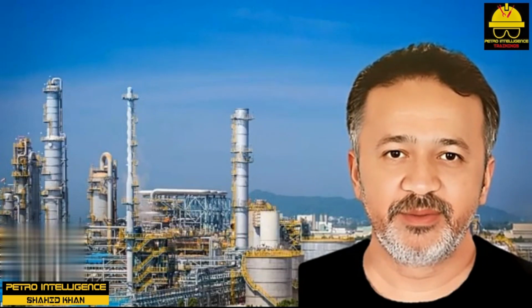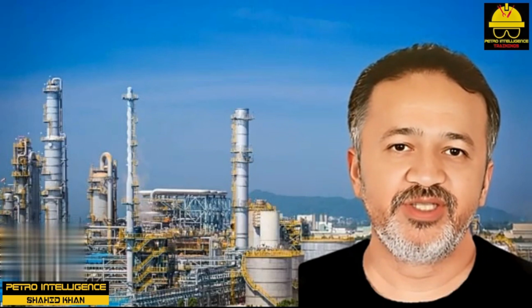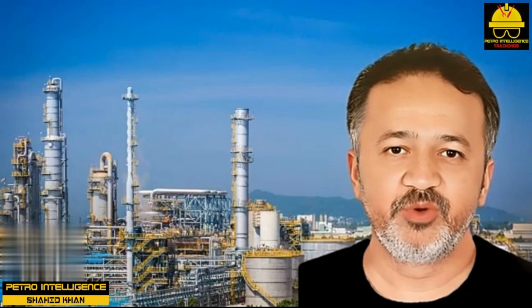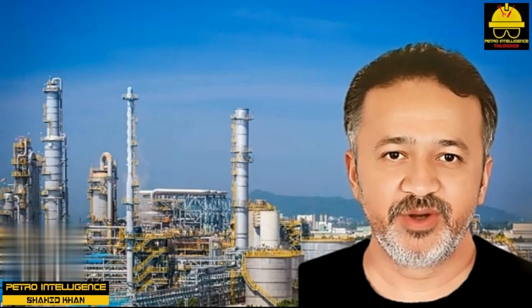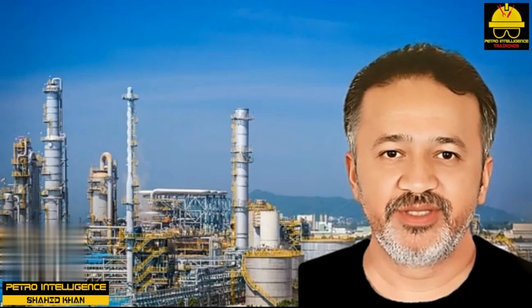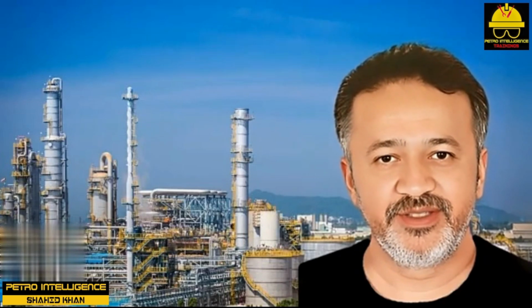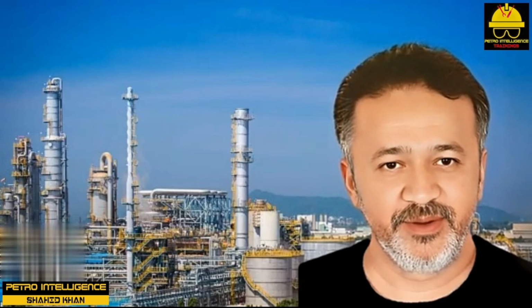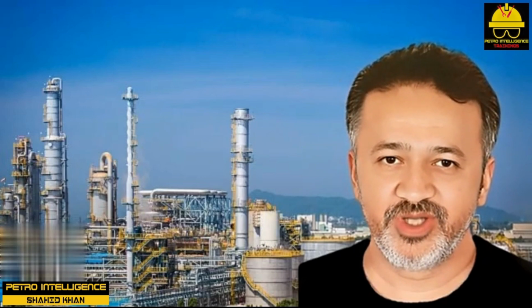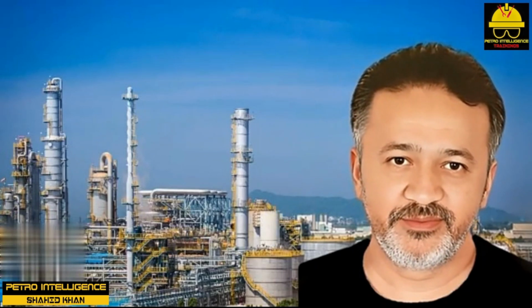All trays with a dynamic downcomer seal suffer from two disadvantages. Loss of flexibility, in that the liquid rates cannot be varied over too great a range without either flooding or unsealing the downcomers. Tray installation complexity is always increased, sometimes with terrible consequences. For these reasons, high-capacity trays using dynamic downcomer seals are best avoided on new columns. They should be reserved for use on retrofit tower expansion projects.